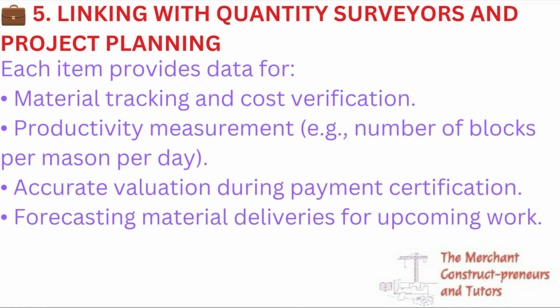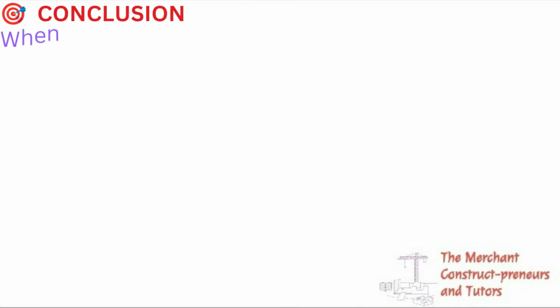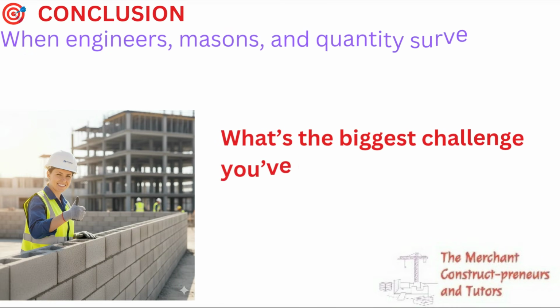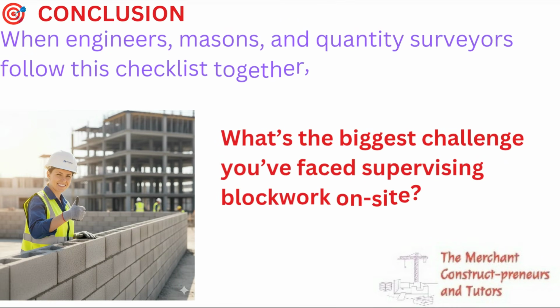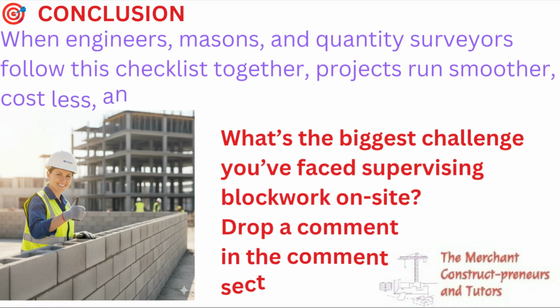Then accurate valuation during payment certification, ensure that the work being done is in accordance to what we are valuing. We don't just pay because people have worked. You need to ensure that they've worked according to what is there and not according to what they plan to do. Then forecasting of materials for deliveries. So without these records, you will not be able to know when next to ask for requisition of materials to come, right?